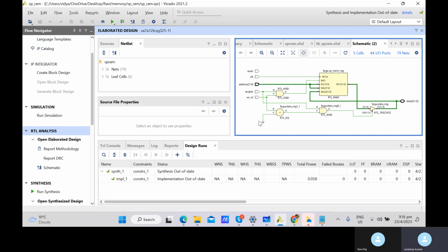So basically, we could not do a write and read together if there is a single data bus. You must avoid writing and reading together. The condition is that when we are writing, at the same time read should be driving Z, and when we are reading, write should drive Z. Then the data will occur. Both shouldn't happen at the same time; both enables should be complementary to each other.